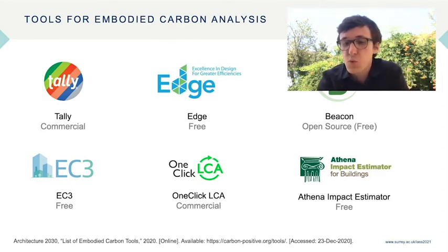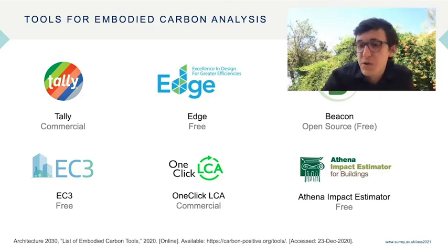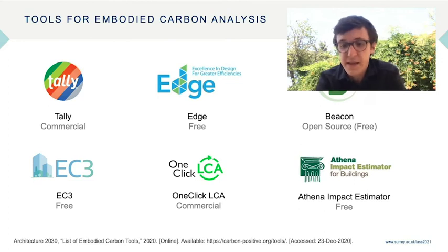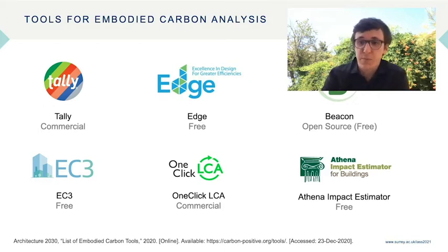There is a plethora of tools and databases available for tracking embodied carbon. Commercial software such as Tally and One-Click LCA plug into existing CAD workflows, while others feature databases with sample projects and materials. All the tools, however, require a full accounting of construction materials, thus requiring a highly detailed BIM model or survey of the analyzed structures. Therefore, they are only accurate at the end of the design process and cannot be used in early stage design or for predictions.